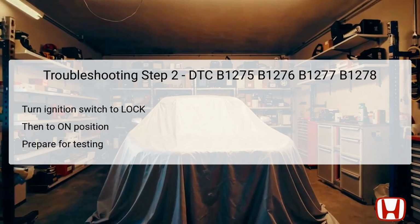In the second troubleshooting step, the ignition switch must first be turned to the lock position, 0, and then back to the on position, 2. This action resets the vehicle's electrical systems and prepares it for further testing.